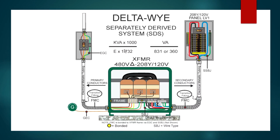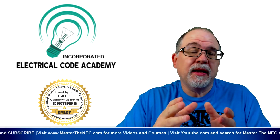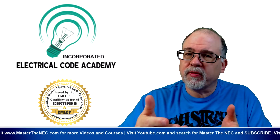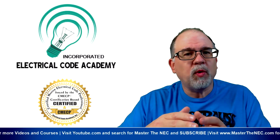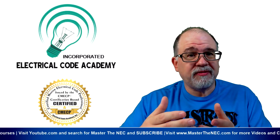First things first, this is the formula right here. You need to get used to this formula. So it's kVA times 1,000 divided by E times 1.732. All right? So let's come back to me and discuss that a little bit. What is E? E is the voltage. What is 1.732? That's the square root of 3. We're dealing with a three-phase transformer, so we're going to need to use the square root of 3. But in this case, it is three-phase in our example.